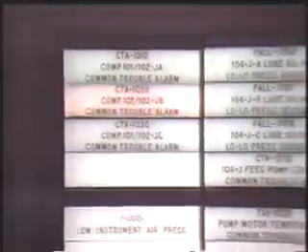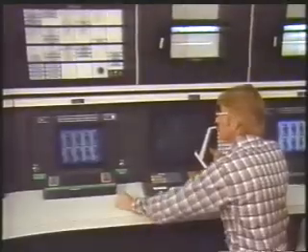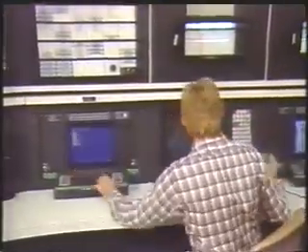The key to safe and efficient furnace operations is controlling the combustion process. In an emergency situation, it might be necessary to quickly shut down the furnace. The best way to do this is to remove the source of fuel. We have seen that by controlling fuel, oxygen, and heat, the operator can control combustion in the furnace.